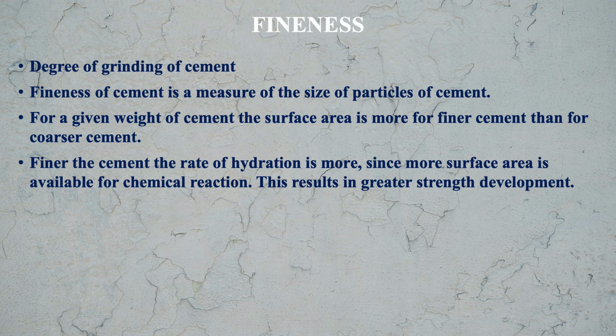Finer the cement, the rate of hydration is more. It means the rate of hydration is governed by the fineness of the cement. So this is the importance of fineness of cement. Since more surface area is available for chemical reaction, the reaction is fast. Rate of hydration is fast. This results in greater strength development.